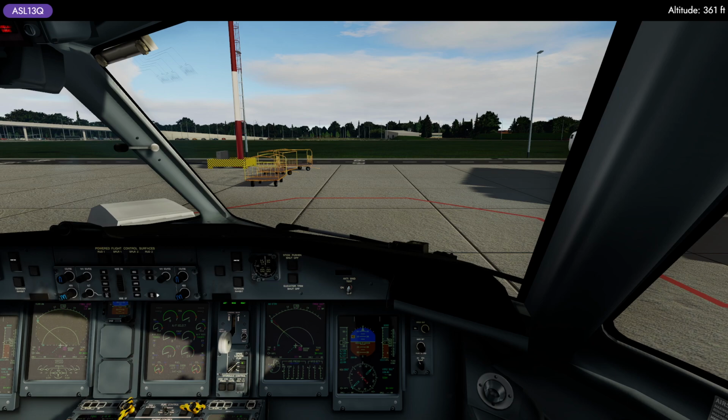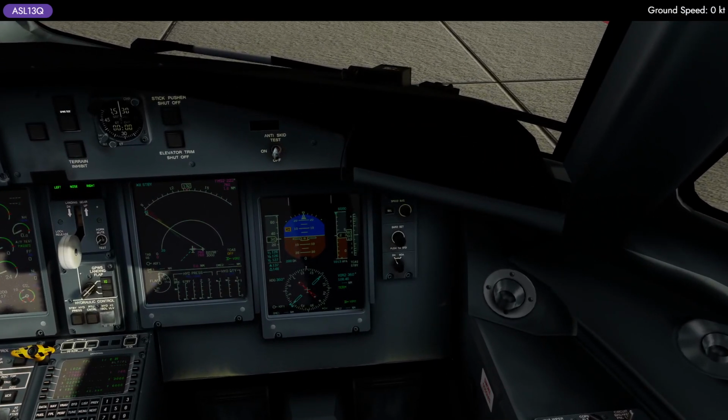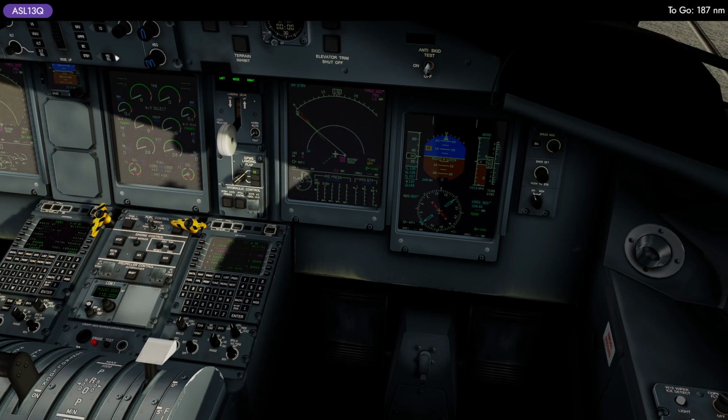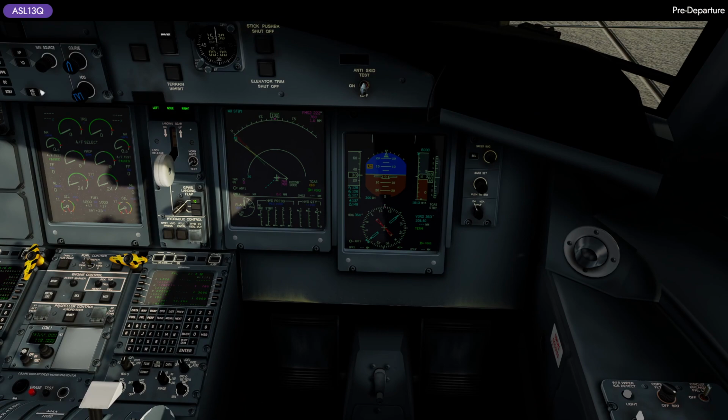Okay, so what I like to do is basically, because the QNH is 1013 for Zagreb, let me just double check that. Yep, so it's a standard pressure, it's 24 degrees, perfectly, everything looks fine. So 370, and I just double check that with the chart.